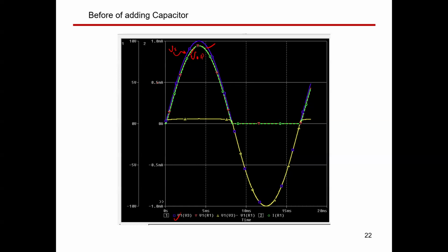Why do we have identical waveforms for the current and volt? Because actually it's not given to the same scale. We have two scales here. If you have just one vertical axis, you will have two different waveforms. But since we split the voltage and current axes, PSpice plotted the two curves as just one curve, because you know that I and V across a resistance are in phase all of the time.